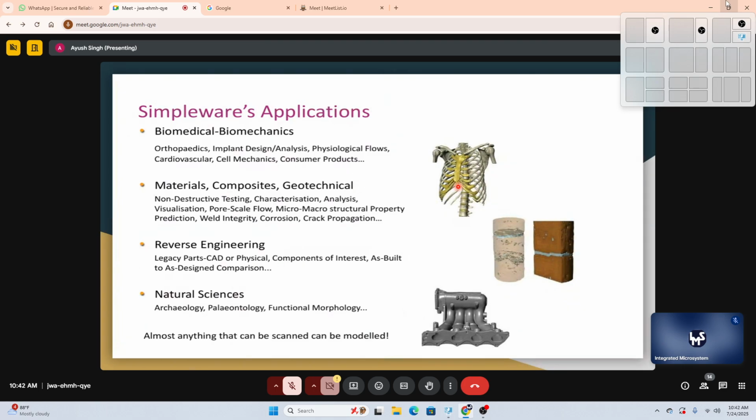We can just have a 3D scan model of the same, input the particular resultant files in Simpleware, do the processing, set out the material properties, and ultimately do the simulation in any simulation-based software. Apart from that, if we need to check any crack propagation, or do the fiber analysis of any fiber-based composite material, that too can be carried out. Porosity analysis can be directly carried out.